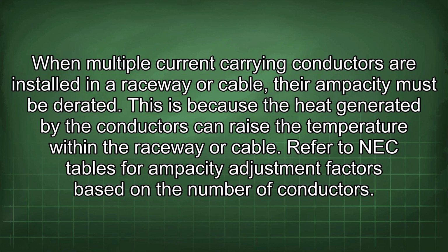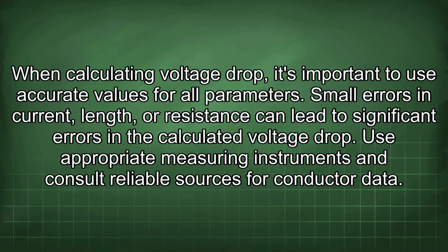Refer to NEC tables for ampacity adjustment factors based on the number of conductors. When calculating voltage drop, it's important to use accurate values for all parameters. Small errors in current, length, or resistance can lead to significant errors in the calculated voltage drop. Use appropriate measuring instruments and consult reliable sources for conductor data.